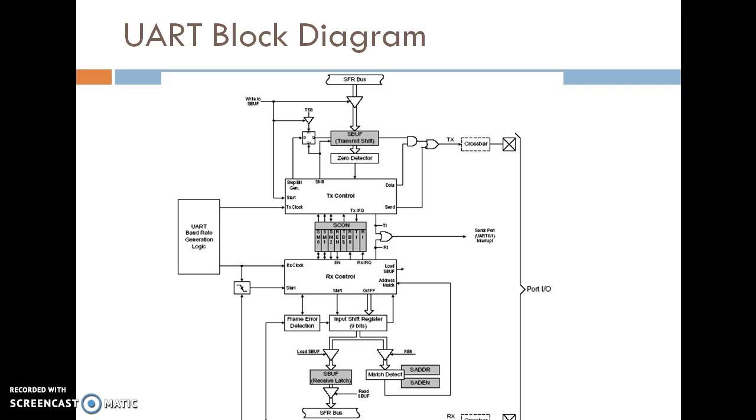The serial port control register contains status and control bits. The control bit sets the operation mode for the serial port and the status bit indicates the end of the character transmission or reception. The status bits are tested in software or programmed to cause an interrupt.